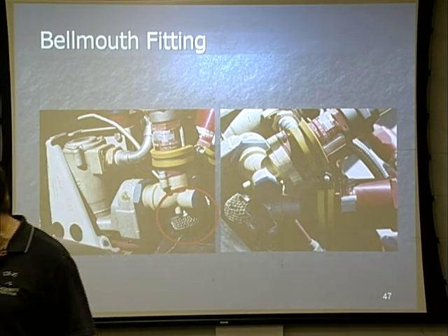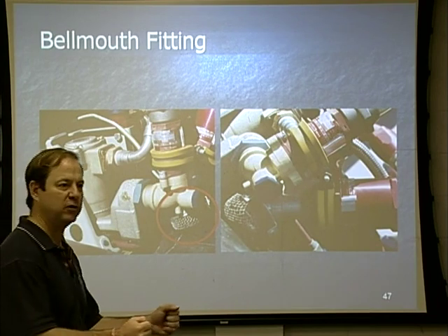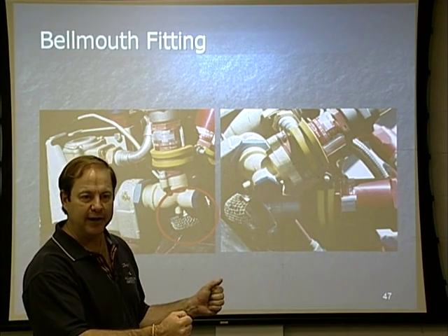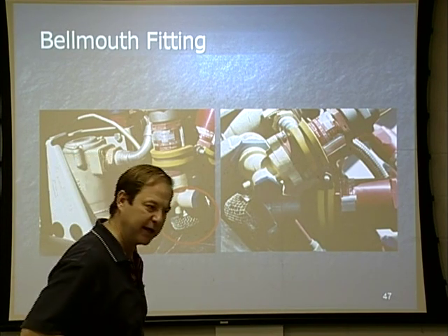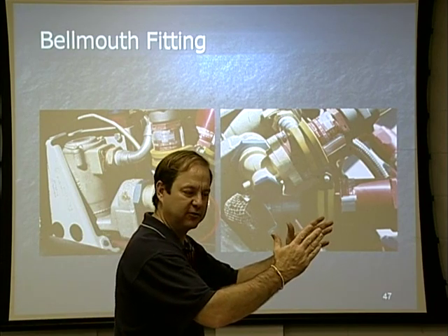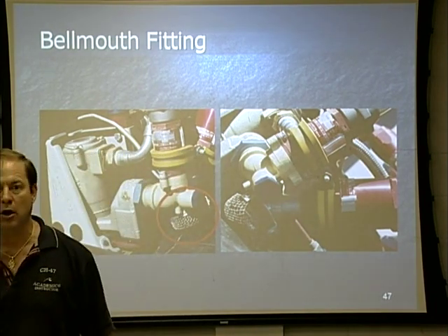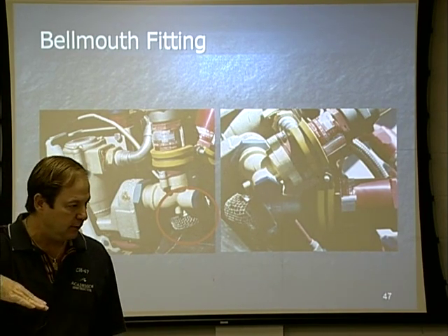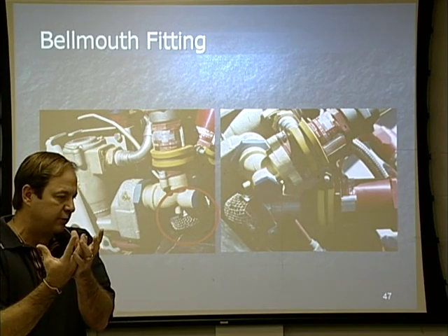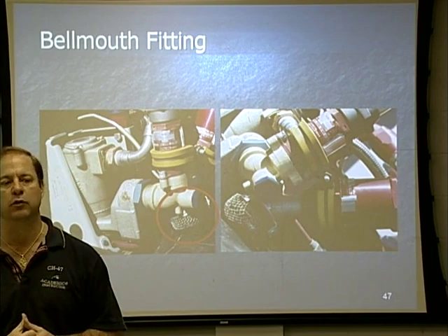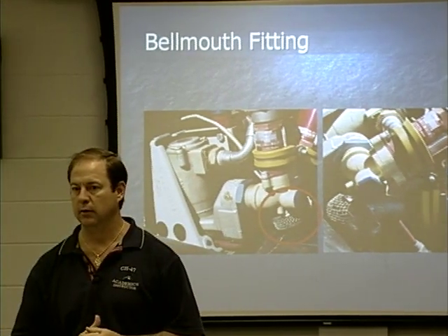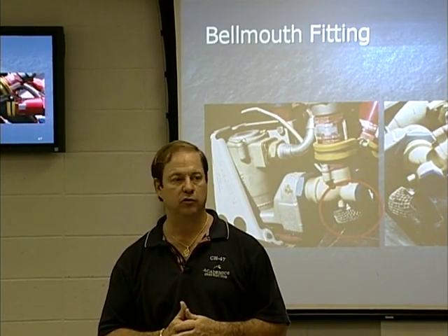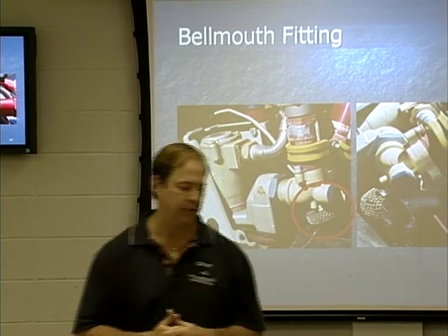But when we tend to get low, what sometimes is our mindset? It's just like what we do in our car, right? Uh-oh, I'm almost out of gas. What do we do in our car? We speed up, and in that way, as soon as I run out of gas, hopefully I've got sufficient speed to coast a good distance. But if I go into 'I've got to hurry up and get there,' and I put this aircraft into a nose-low attitude, and it's using those engine-driven fuel pumps to suck the fuel out, now what's going to happen is we're going to suck air into that system. And we will end up flaming the engines out based on where that bell mouth fitting is. Any questions about that?